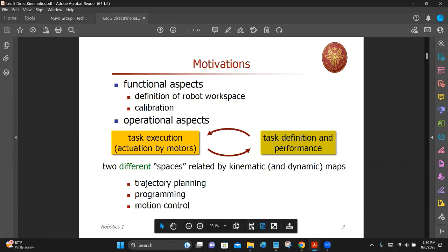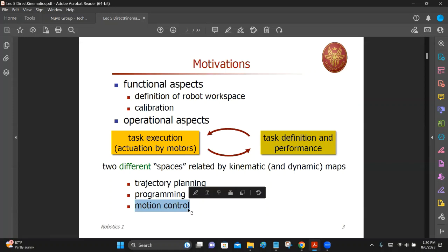Okay. Then comes motion control. So once you plan your trajectory, you are asking the robot controller to drive all of these joints, maybe 5 joints, to a certain angle initially. Maybe you can start with 0, 0, 0. So all zeros, right? So it may be vertically upward position of the robot or vertically downward position of the robot, right? So that is your start point. And then from there onwards, the data file has the 50 millisecond position updates, coming from what you have already programmed.